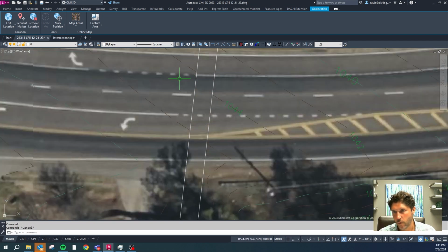So this one's 44, and assuming that would go like that, this one is 46, that one's 48, this one is 6.1 feet out of 28.3. 6.1 divided by 28.3 is 21%, 0.2, and 0.2 of a 2-foot contour, because this is a 2-foot contour from here to here, that's 0.4 feet.